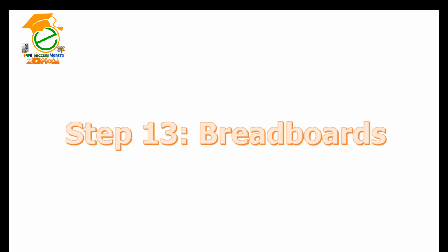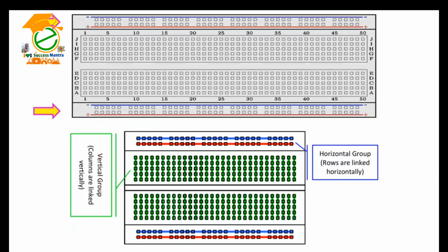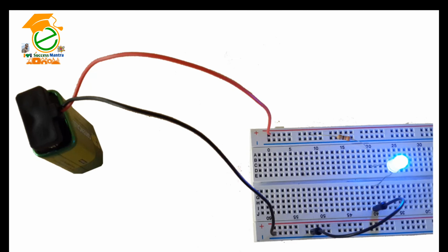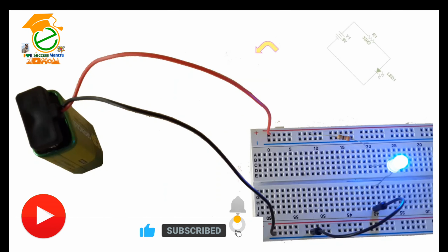Step 13. Breadboards. Breadboards are special boards for prototyping electronics. They are covered with a grid of holes which are split into electrically continuous rows. In the central part, there are 2 columns of rows that are side by side. This is designed to allow you to be able to insert an integrated circuit into the center. After it is inserted, each pin of the integrated circuit will have a row of electrically continuous holes connected to it. In this way, you can quickly build a circuit without having to do any soldering or twisting wires together. Simply connect the parts that are wired together into one of the electrically continuous rows.